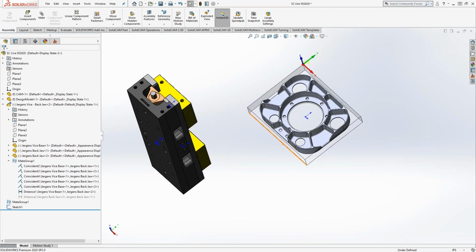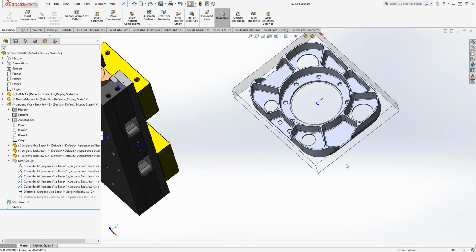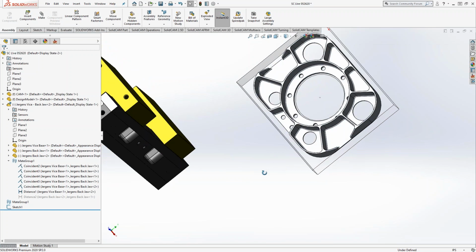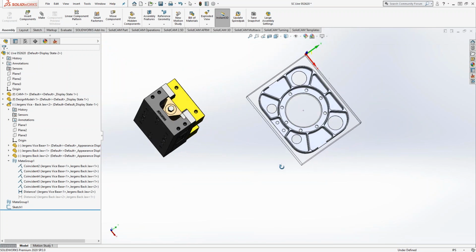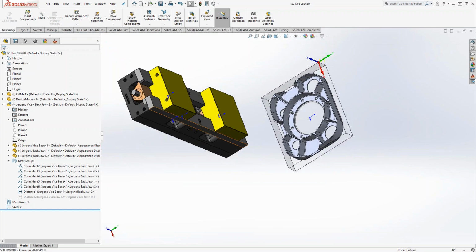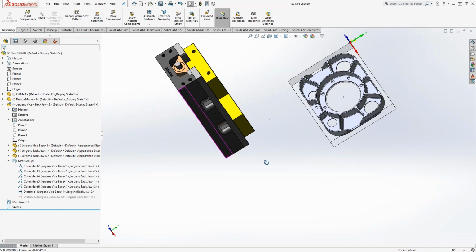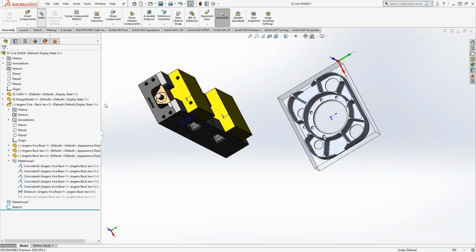Taking a look at it, I probably want to hold it on this side and this side, because that is an open pocket there, and I'd like to take advantage of the openness there. So let's see, yeah, okay, let's do that. Plus, that's how I will go. Plus, that's exactly how your coordinate system is set up. So that vise would be in the y-axis. Yeah, that too. Okay, so let's go to mates.